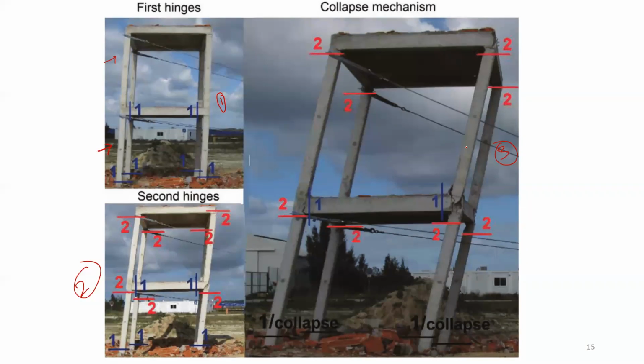Once there is a formation of the plastic hinge, the deformation or collapse of the structure will take place. Now in the figures, you can see the plastic hinges getting formed. See, this is a plastic hinge. You can see mild cracks on the surface. Here also you can see mild cracks. And then the failure happened.